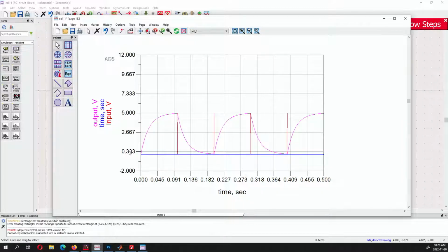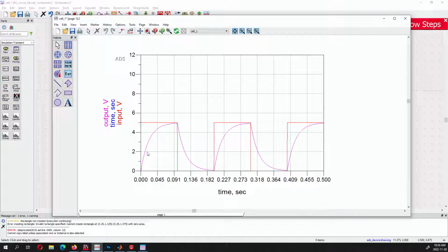I'm just going to manipulate this and put this as 0. So it's going from 0 and reaching 5 volts. It's not yet completely 5 volts, it's at 4.77 volts, and we'll see how accurate this is in the real life example. So with the ideal situation of an RC of exactly 47 microfarad with a 463 ohm resistor, you're looking at this type of graph.